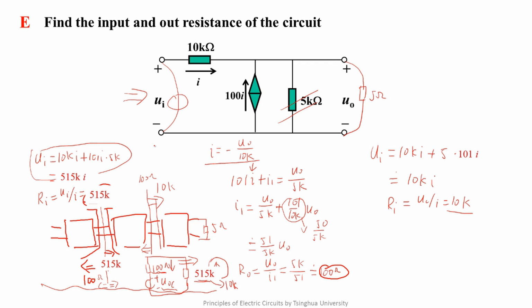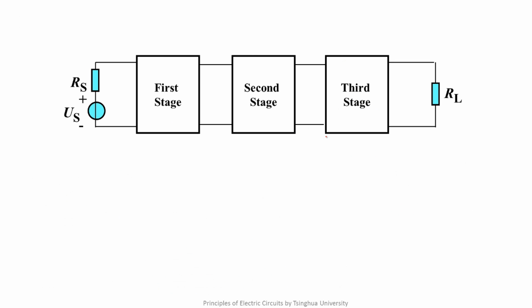When we discuss the input resistance of the voltage signal processing circuit, sometimes we should consider the load resistance, sometimes we needn't. So, in what condition should we consider the load resistance, and in what condition we needn't? Usually, if the input resistance of the voltage signal processing circuit is still relatively large comparing with the load resistance taken into account, we can ignore the influence of the load resistance.